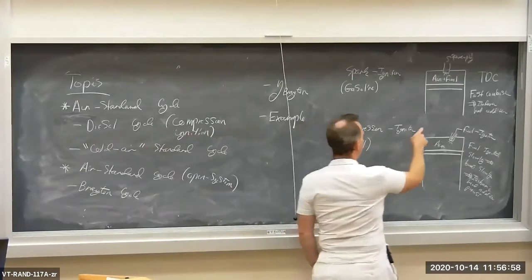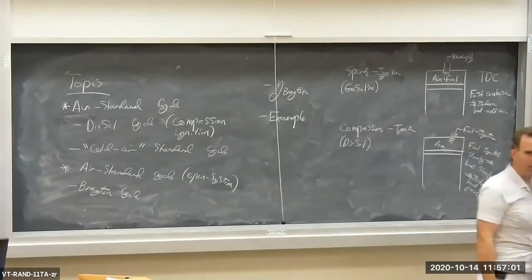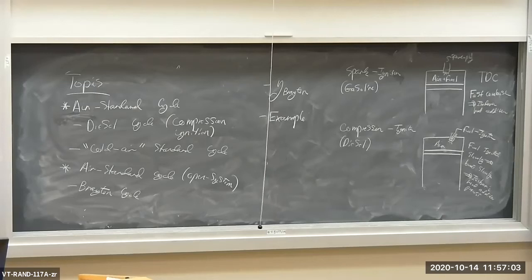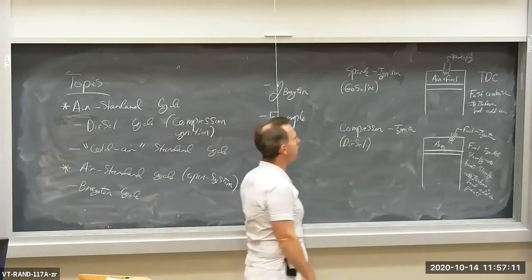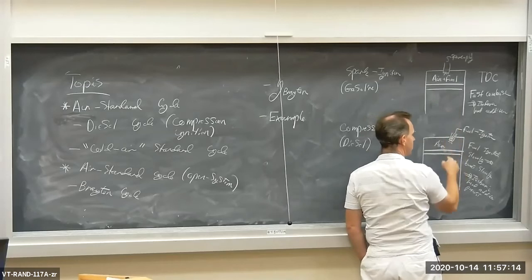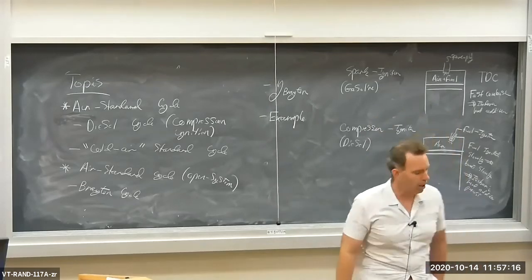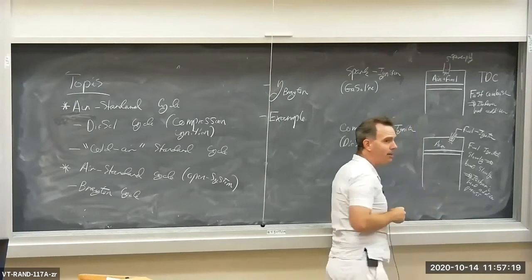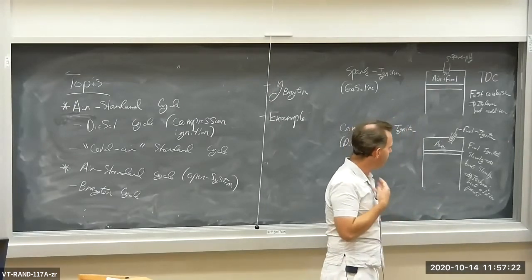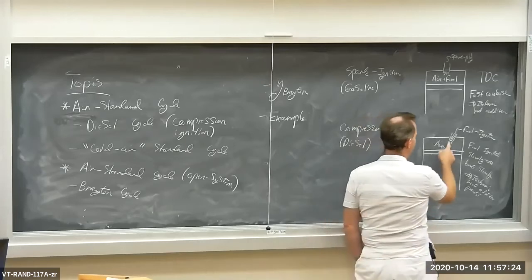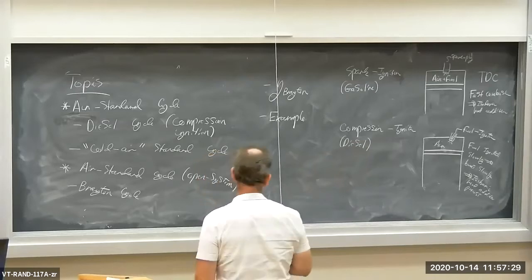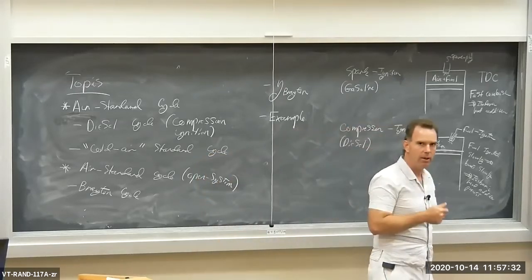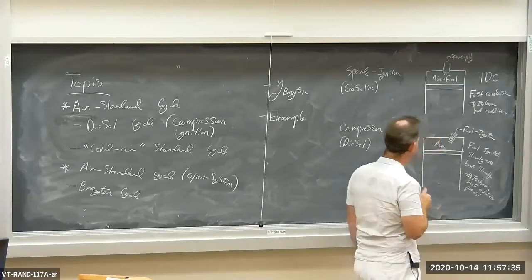For the Otto cycle, we start off with an already mixed air-fuel mixture, and then we initiate a spark and the heat is released essentially all at once, very rapidly. So we approximate this as an isochoric heat addition process. But for the diesel, we start off with compressed, i.e. very hot, high pressure air, and then we inject fuel via a fuel pump with a fuel injector into the combustion chamber, into the hot air, and it starts to burn as soon as it hits that hot, highly compressed air.